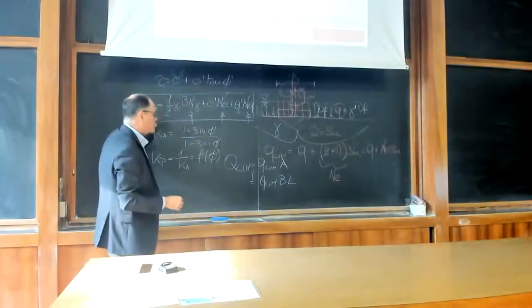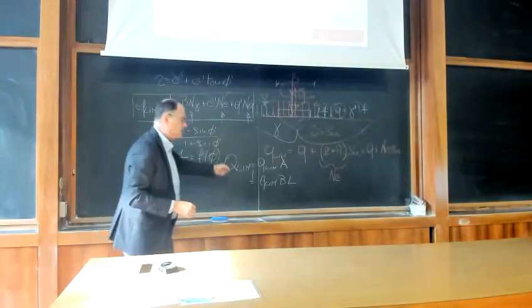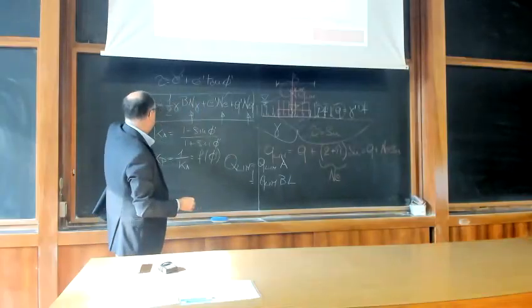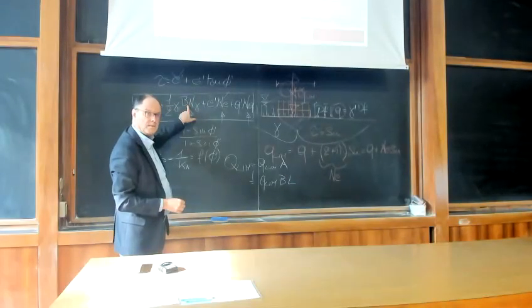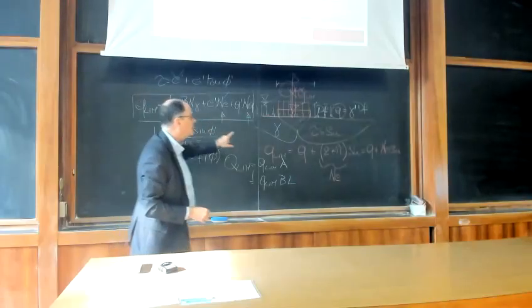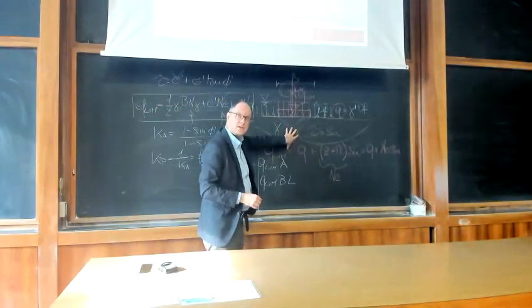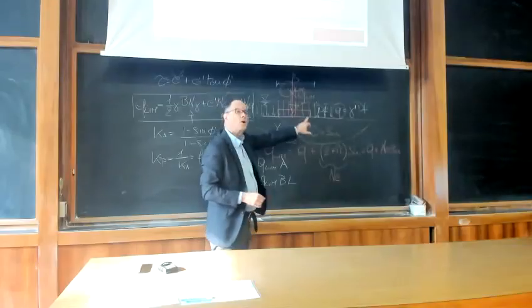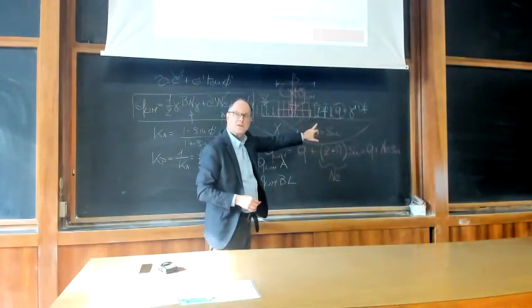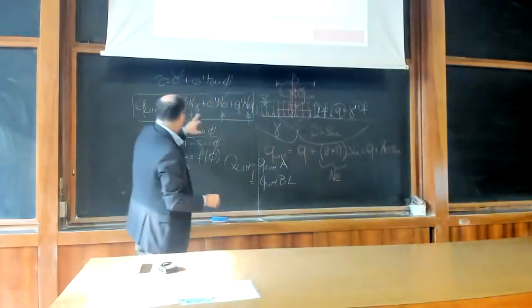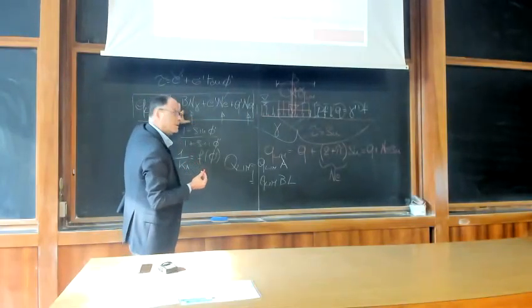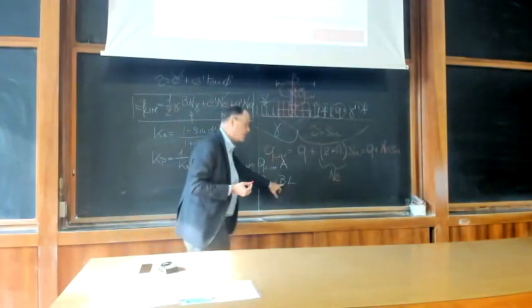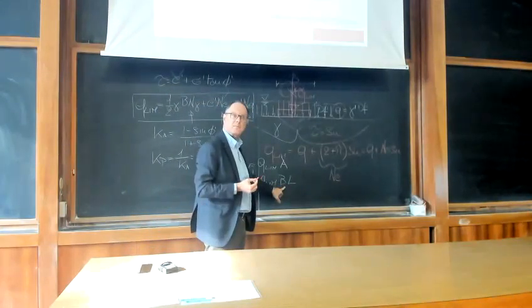But here we are not saying this. We are saying that the unit pressure depends on B as well. So not only on the soil characteristics, but also on the footing size. If you think about it, the footing breadth counts twice. Here for the unit pressure, and here as part of the area.